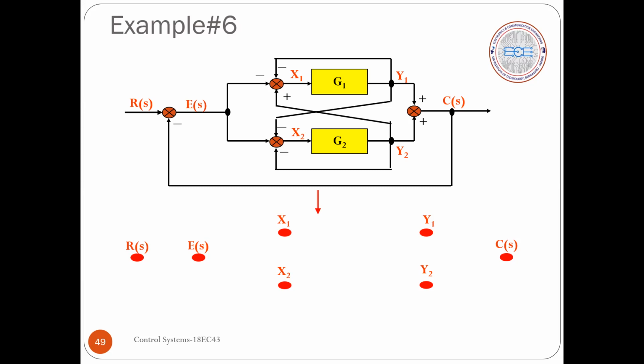Okay, so here we are trying to retain the block diagram representation as it is. So we will see how many nodes we require. All the summers will form a node, definitely. I have first summer here, 1, 2, 3, 4. So 4 nodes we have because of the summers, and we will be having takeoff points. Here we have takeoff points, 1, 2, 3. Okay, so there are 6 nodes essential, and input node, output node, we can merge to the neighboring nodes, but we have taken here explicitly the input node, whereas the output node we are merging to the takeoff point we have here.